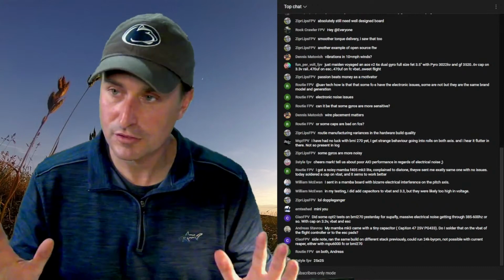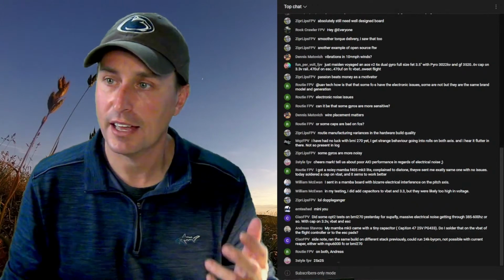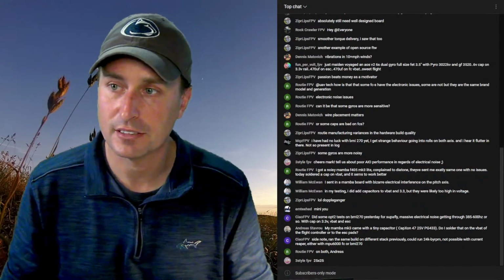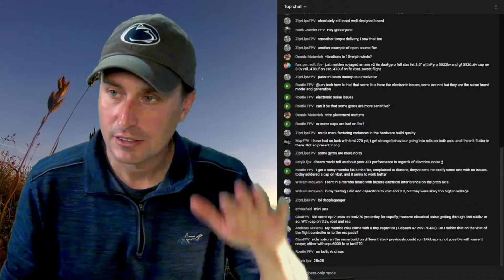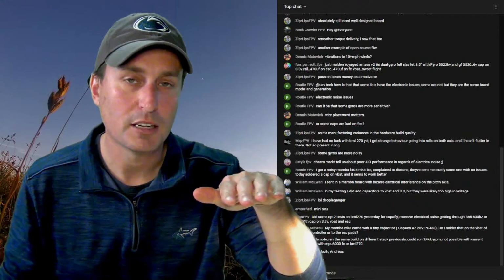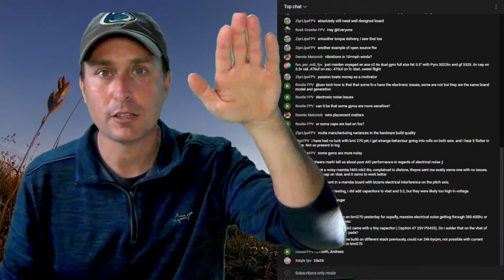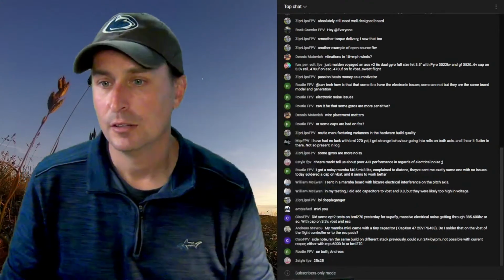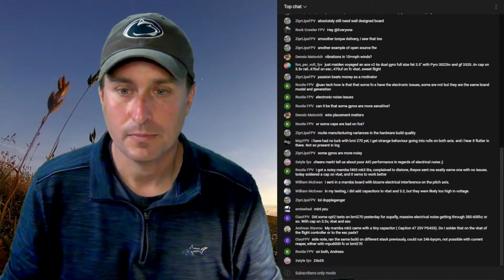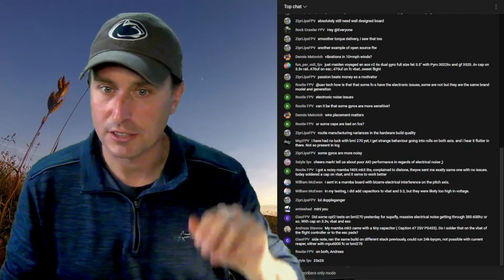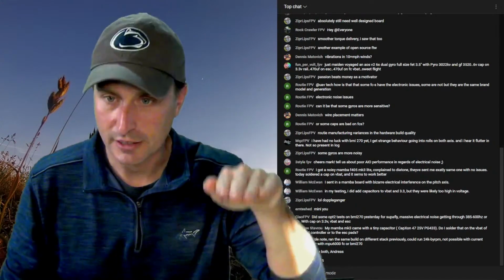KISS is fine, but it doesn't have a couple of things that Betaflight does. And the biggest one is anti-gravity. It doesn't have any anti-gravity code. So when you hit 100% throttle and then jump off the throttle, you'll see the nose kind of move. In Betaflight, that doesn't really happen that much at all. It's maybe a slight shudder, but you don't see this big dip.